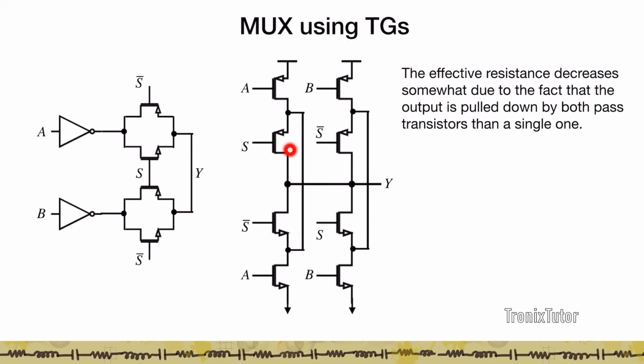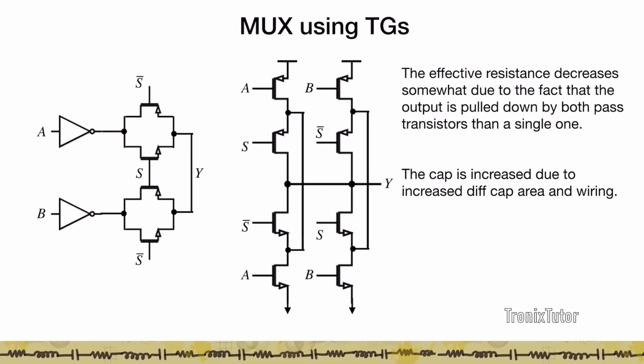And so generally what we see is that the delay that we estimate using the CMOS configuration tends to be of the same order as what would happen in reality. In reality, the gate delay would be slightly less than what is estimated here. And that is primarily because of these additional connections, you end up creating junctions which are of higher capacitance. The wires also introduce a certain capacitance which compensates for the increased drive strength of the structure. So essentially the delay that you get in this structure using CMOS is the same as that using transmission gates.